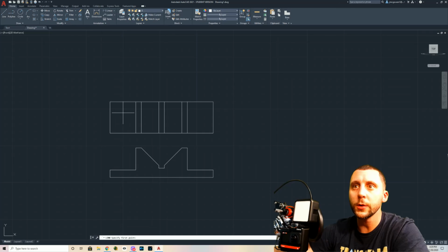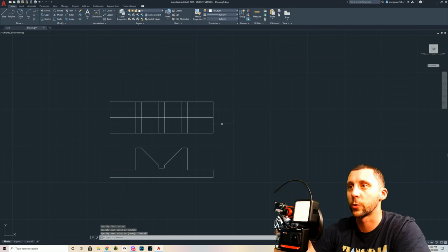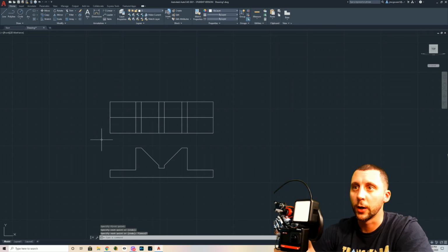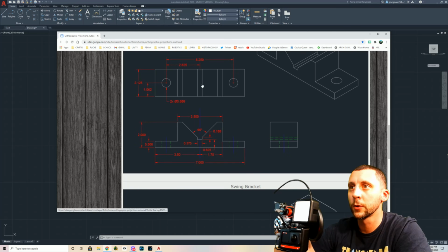Now I'm going to put a line down the midpoint. Midpoint to midpoint, this is a dummy line. I need this in order to get the circles, okay? The circles are from the center, from this blue line, which is the center of the entire drawing. I'm going to go, let's see, where's that number? 2.625, 2 5/8 to get to the center.